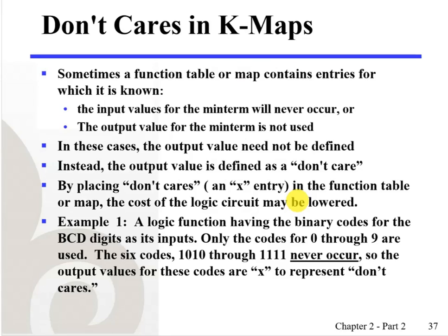One of the very useful concepts in simplifying the output expression using the K-map is the concept of don't cares. These don't care conditions in a K-map allow us to fill empty cells so that we can form larger groups than forming groups without don't cares.